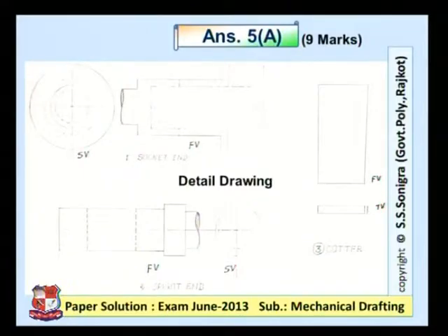And here in the detailed drawing, you can see these dotted lines are represented. These dotted lines represent the inner portion because sectional view is not drawn here. In side view, circles would be there. In spigot end, this would be the spigot end, and this is the cotter of given assembly. The cotter is drawn slightly taper over here. So because of the taperness of this edge, here you have to draw 2 lines, this full line and a small dotted line over here. This small dotted line represents this edge, and the distance between this full line and dotted line shows the taperness of this cotter.